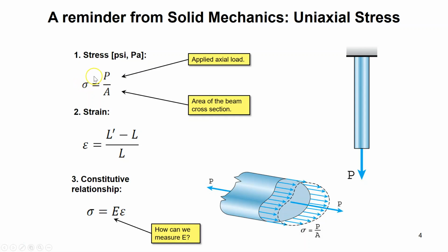And this is called a normal stress. We show it with sigma, and the reason we call it normal stress is because this force P that you see is normal to that surface, is perpendicular to that surface, so we call it normal stress. And the effect of normal stress is clearly what? If I apply a normal force P like that to the rod, what do you expect to happen?